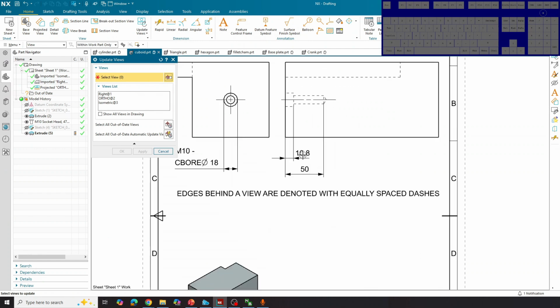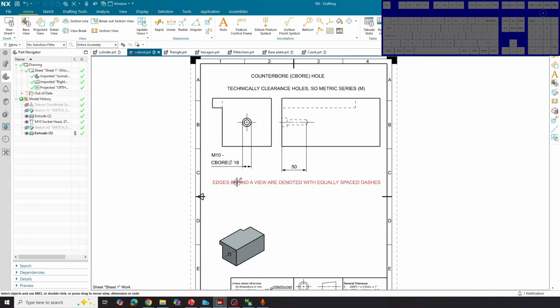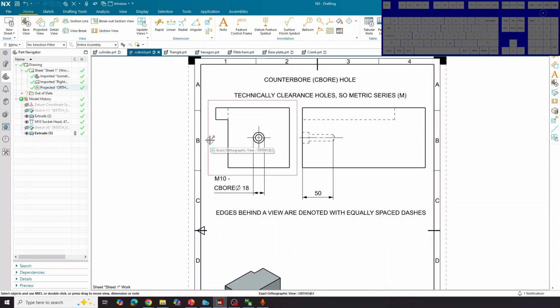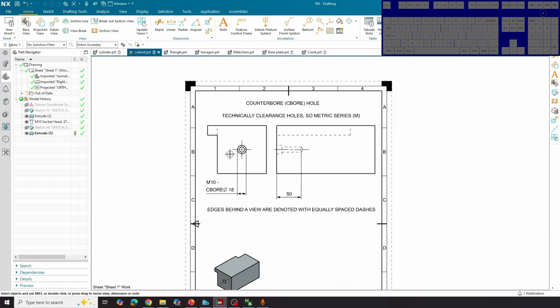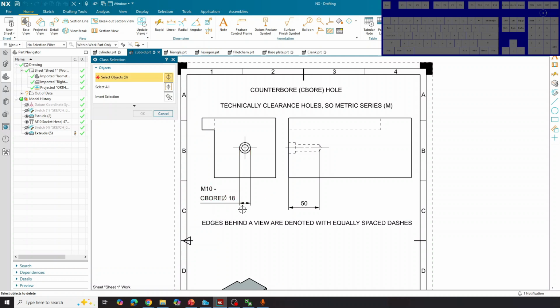Okay, so just as an update, it turns out that we don't need the bore depth because it will be given in the tool settings itself. So all you need to focus on is just the counterbore, the hole size, and the depth of it as well. And you won't need to focus on the bore diameter either. Just go onto the hole settings, click on M10, and then specify the depth of it as well.